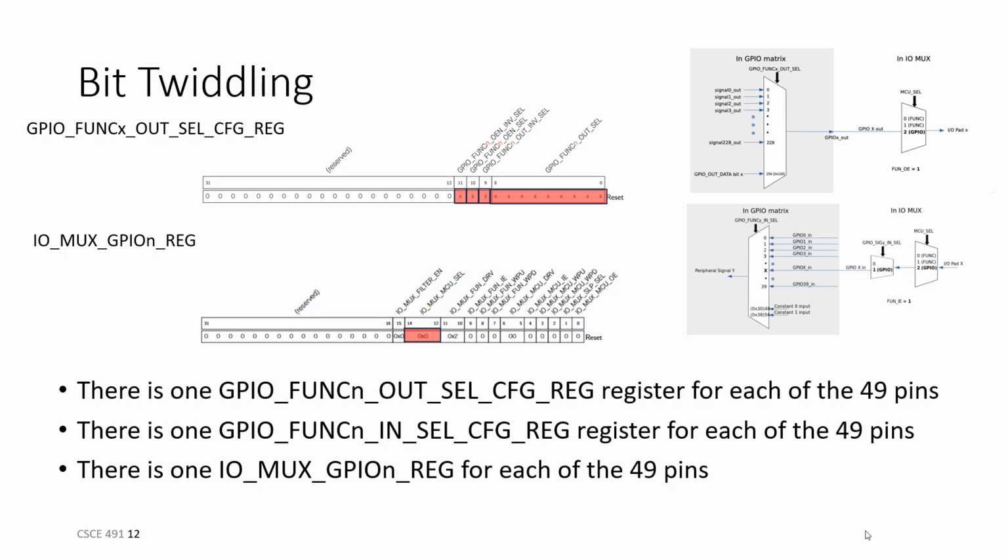But in this case, we don't want a digital write because that's bit banging. We want to control the pin with the peripheral, the RMT or LEDC. So we want to use the codes for those, which I have in the lab sheet. There are codes for LEDC and RMT, of course, and which channel of each as well. Those are codes for the GPIO matrix.